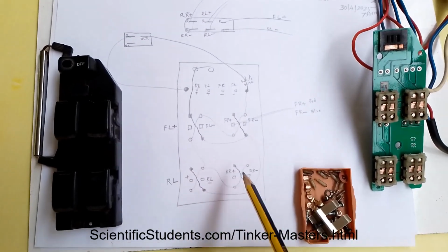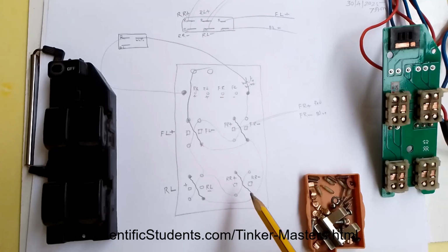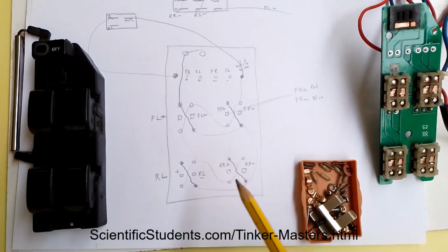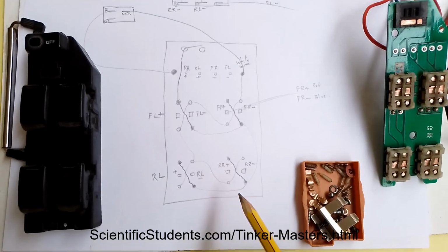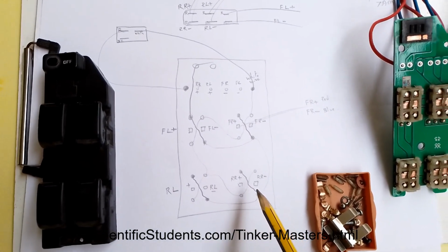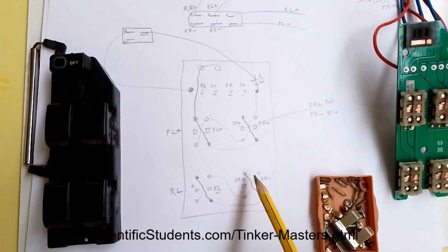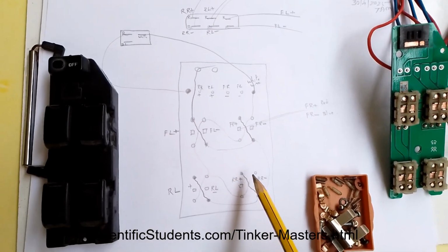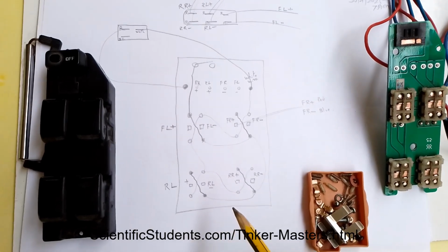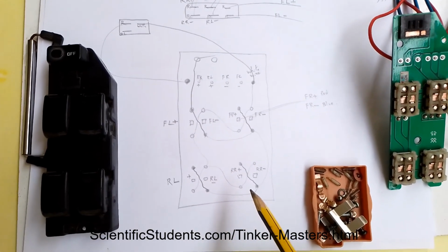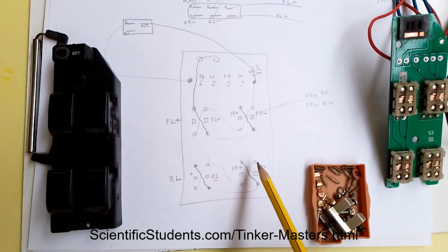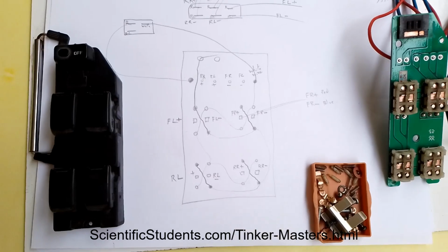There are 4 momentary switches. They are all kept disconnected when you don't push it down or up. Okay, so they are off. They are off in center, but if you press down, these motor connections will get connected to battery connections. So when you again leave it, it will come back and stay at the center. It will not connect, the poles won't get connected to any of these battery connections.